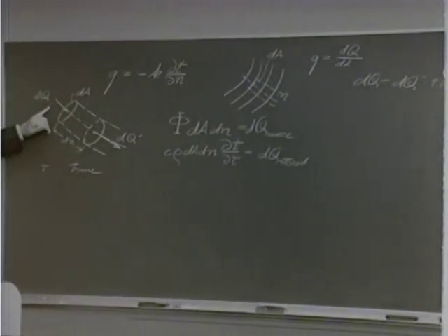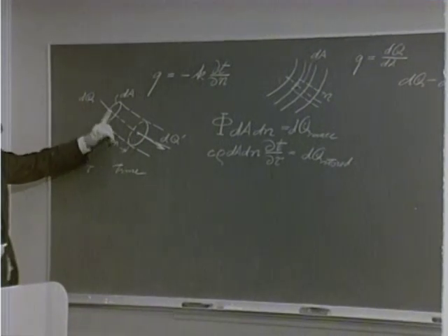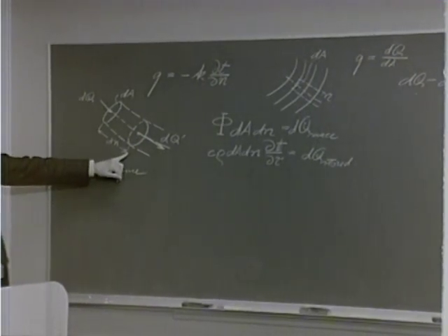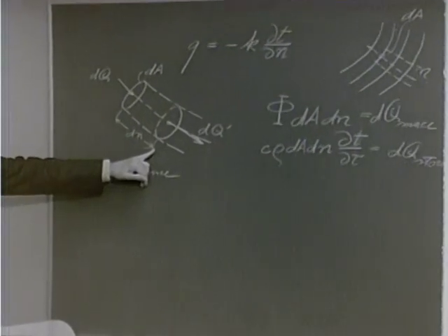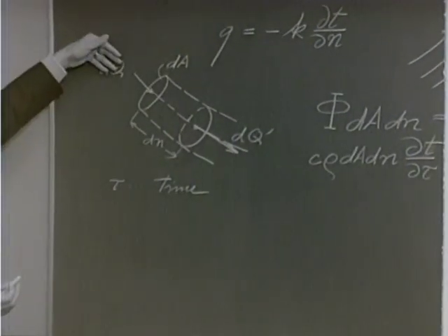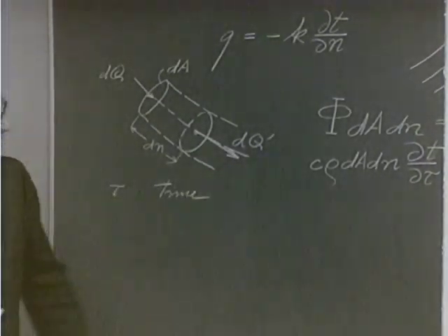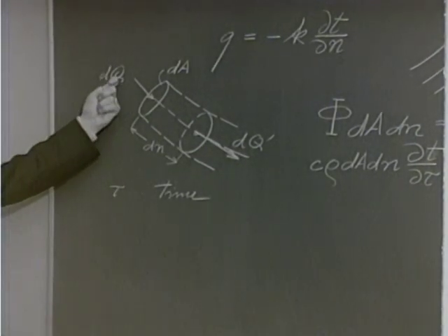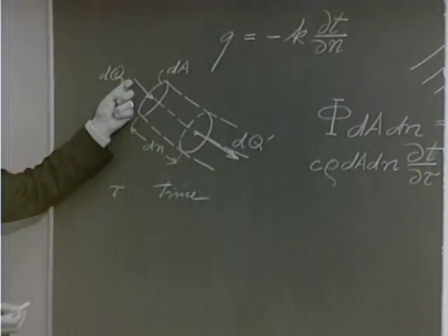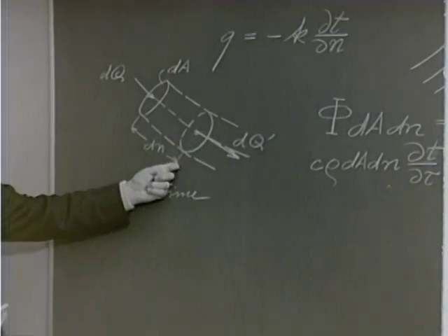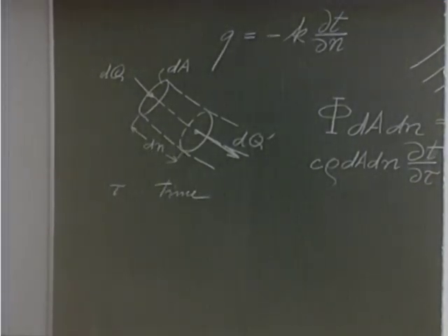We want to find the difference between two quantities, two fluxes, which are a very small, an infinitely small distance apart. And since the heat flux can obviously change only in a continuous way, then the change from this quantity to this quantity, because it occurs only on an infinitely small distance, can only be a very small amount.